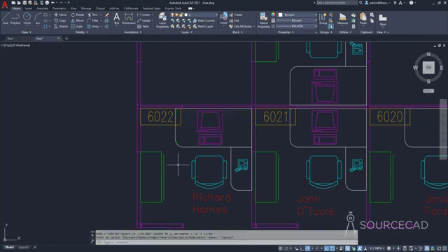Now if you want to combine areas, if you want to find area of multiple regions in your drawing, then you can use this command. I'll go to this area again, and in this case I'll find out the area of this table as well as this one. I'll start with this table, but first let me check if I can find its area directly, because here I just need to ensure that this table is also a single object.